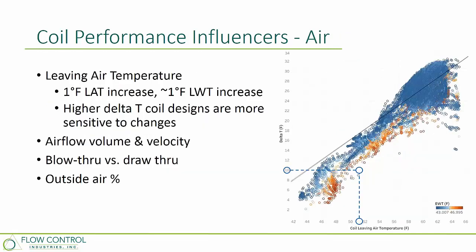On the air side, there's another impact there as well, right? So entering water temperature is probably the biggest impact on the water side. Leaving air temperature is probably the biggest impact on the air side. And if you think about a coil and the way a counterflow coil is configured, those two parameters, entering water temperature and leaving air temperature, are right next to each other on the outlet of the coil. So that's why they have such a big driving influence.